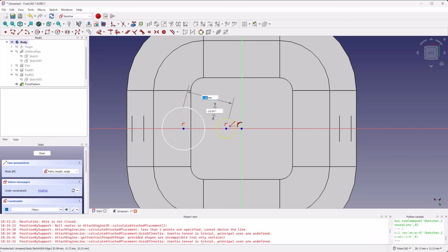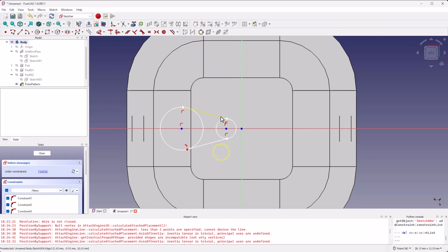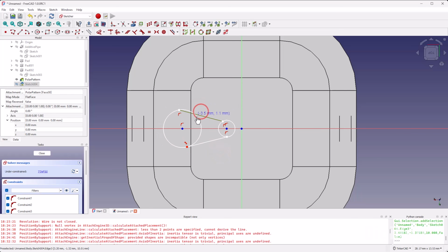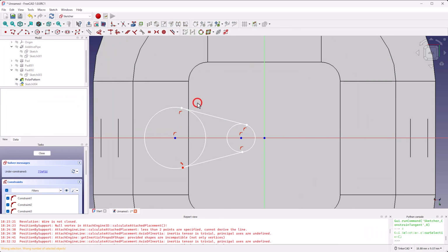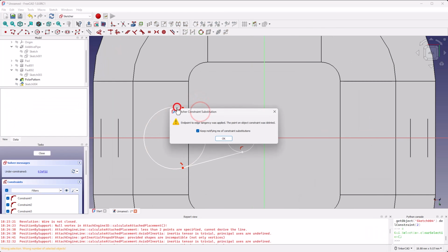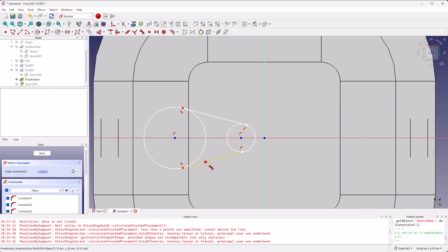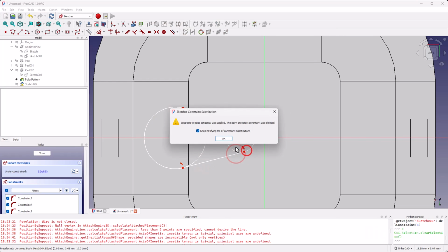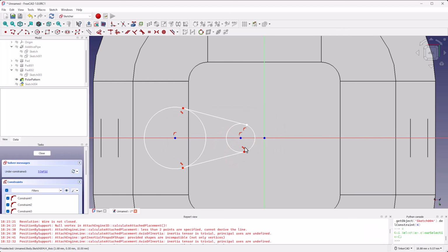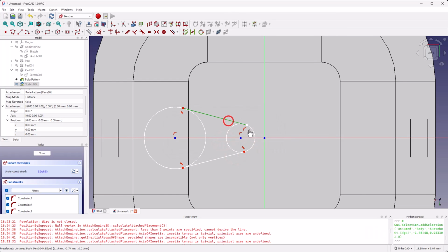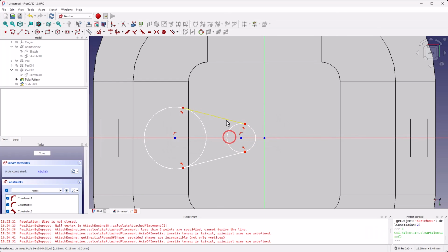I'm going for a teardrop shape here. We're going to connect this to this. Right click. These can kind of move around, and what we want to do is press T for the tangent tool. We want this to be tangent to that. That's okay. It looks like that already applied down there. We want this to be tangent to that. That's okay. It's just taking away that coincident constraint and replacing it with a tangent constraint. And now we've got this teardrop that we can play with.